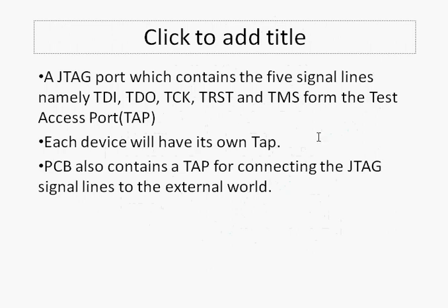Every device which supports JTAG should have this TAP. This test access port should be made available for every device which supports JTAG, and the PCB on which you lay the devices should also include this TAP feature for making the connection happen.